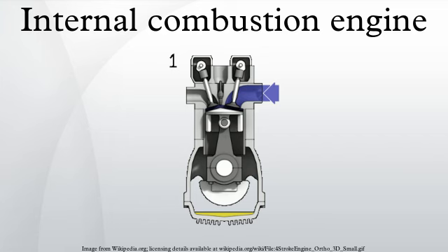Disadvantages: the lack of a lubrication system that protects the engine parts from wear. Accordingly, two-stroke engines have a shorter life. Two-stroke engines are less fuel efficient and produce more pollution than four-stroke engines. Also, sometimes part of the fuel leaks to the exhaust with the exhaust gases.